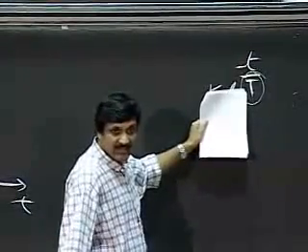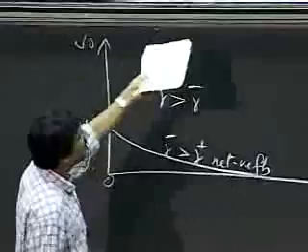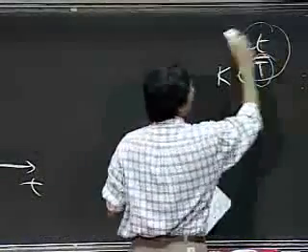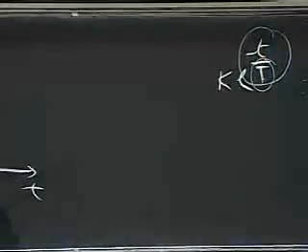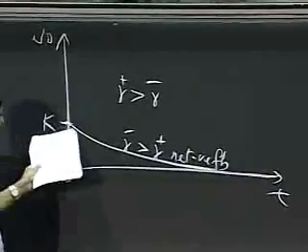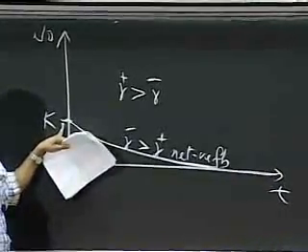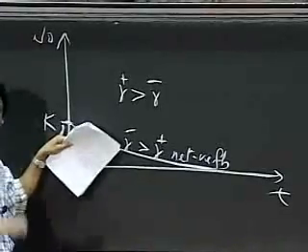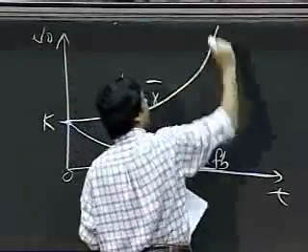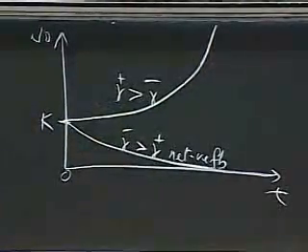Now, we cannot see this happen in an RC circuit because capital T is equal to RC. But here we have a more complicated circuit, and capital T can go negative. If capital T goes negative, then this whole thing in the exponent goes positive. If that goes positive, what should the output look like? It should go up, it should take off into never-never land.